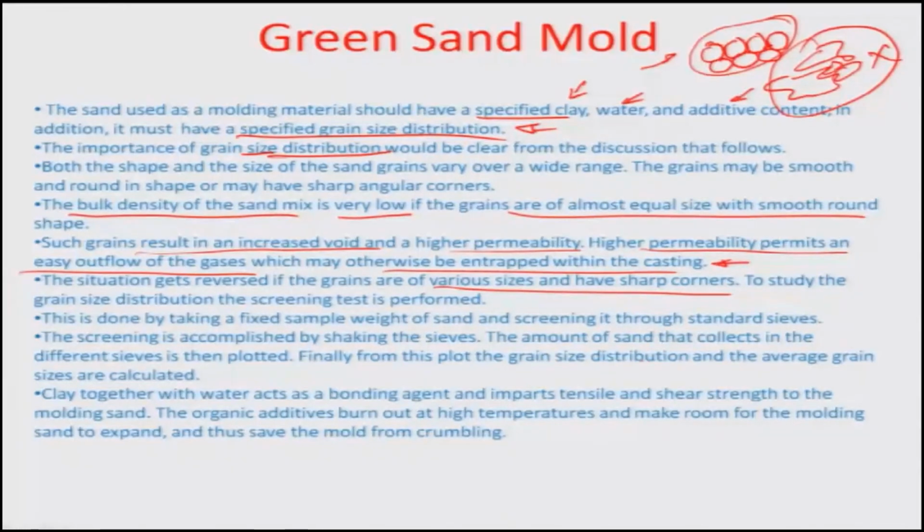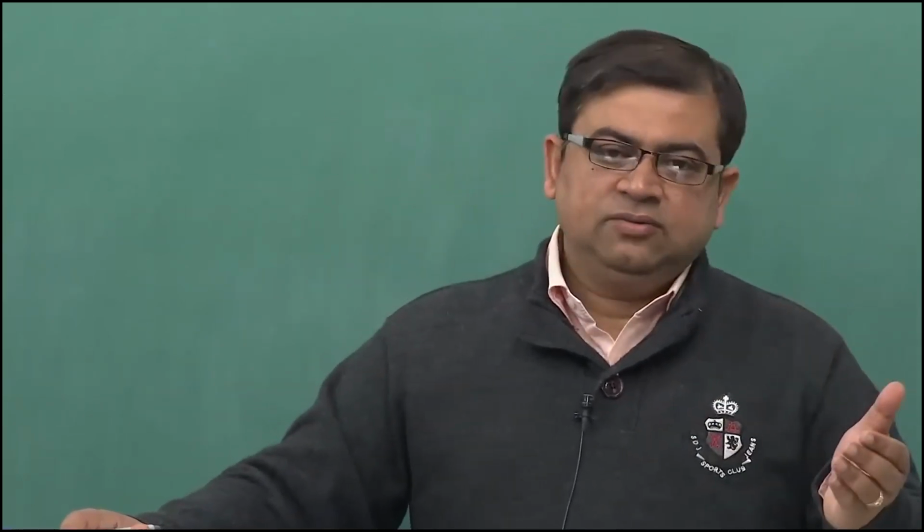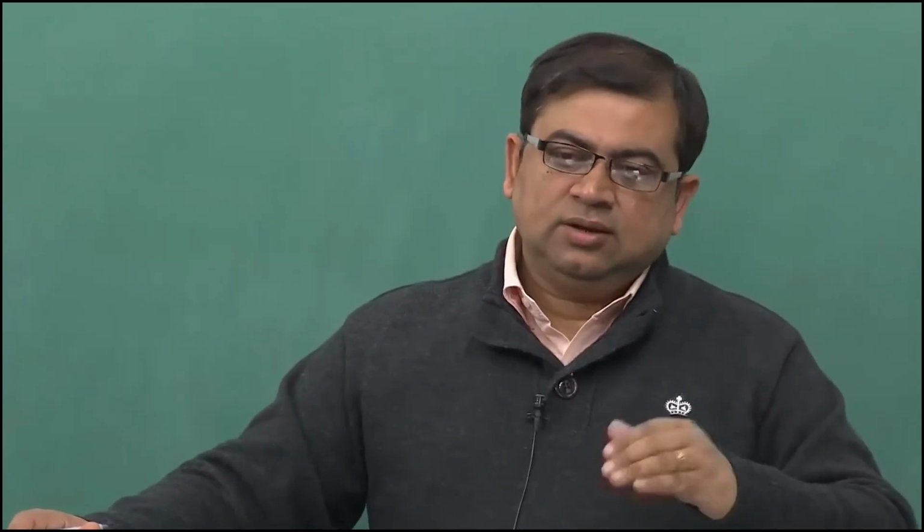So, how do you actually do the size-based separation of the sand grains? You pass it through sieving matrices of different dimensions and collect different grains, so that you can categorize a grain as some grit size, or below some grit size. Basically, all grains of a higher size than the grit size would be retained, vis-a-vis all the grains of a lower size than the grit size would pass through the particular sieve.